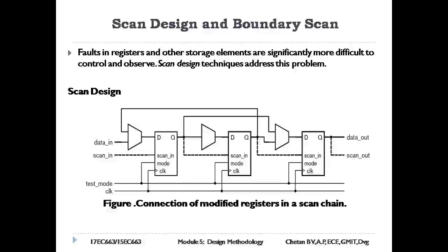The test equipment controlling the process compares the output values with the expected results to detect any faults. This sequence is repeated until all of the test vectors have been applied to all of the combinational blocks or until a fault is detected.